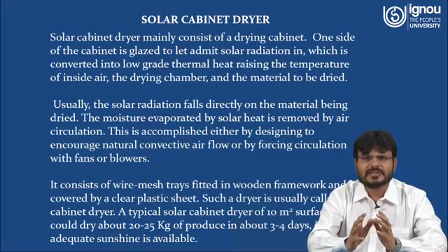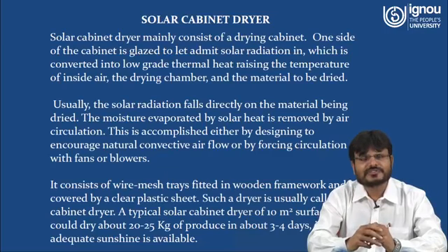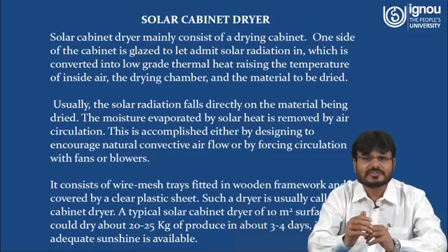So what will be the advantage of the natural? No additional equipment is required, like you don't need a fan. It works on the natural process, that means it works on the thermosiphon principle. And the second type is forced circulation. As the name indicates, the circulation is forced. For this type of circulation, you need some blower or fans.